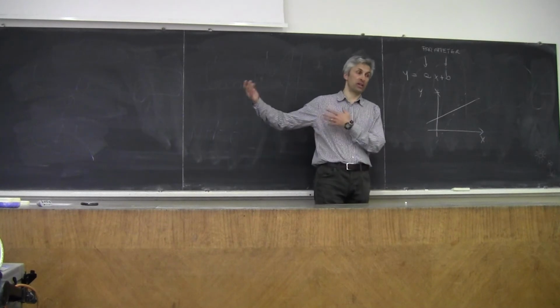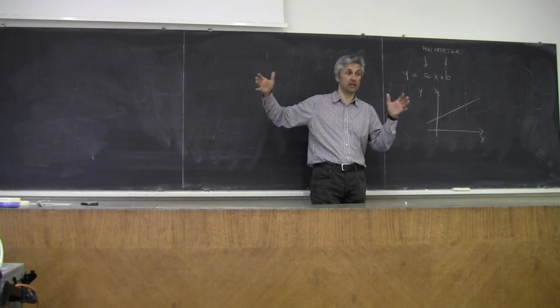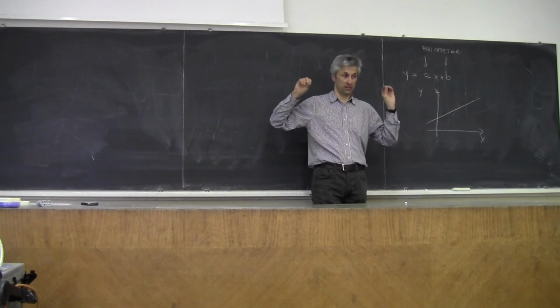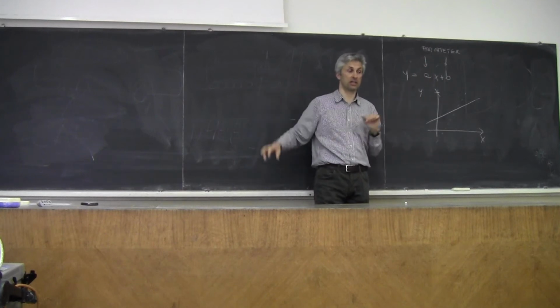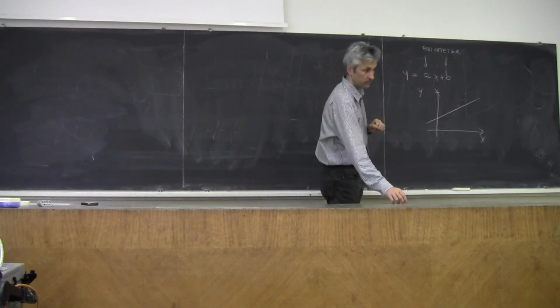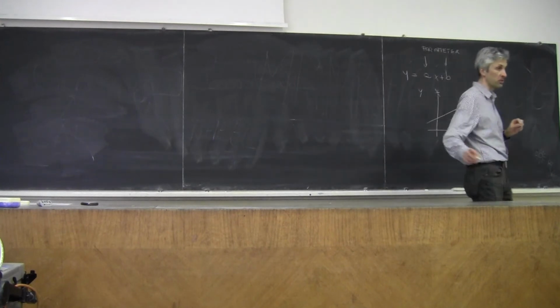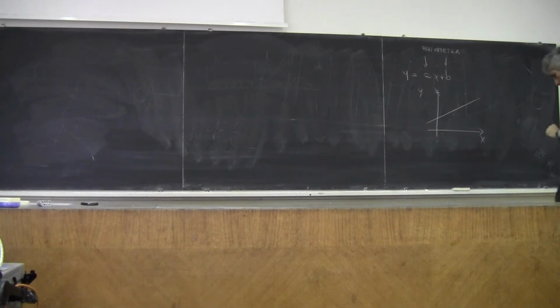So, going back to our case, the model is the time area method. But the specific response of this model depends on its parameters, and in particular one parameter is C, the runoff coefficient. In fact, to apply this model, we had to fix a value for the runoff coefficient. On Friday, I gave you the text of the exercise where a given value of the runoff coefficient was proposed. Okay.